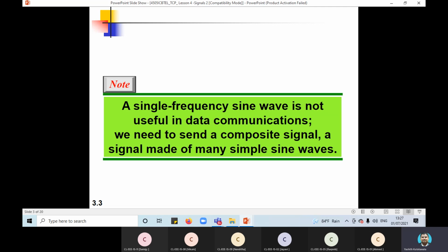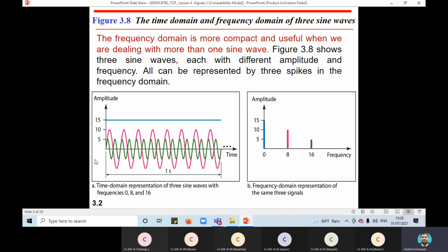the signal needs to be discrete, somehow having some constant voltage levels, a high level and a low level. Then according to the high level and low level, we can assign digits. Once you assign a logic to these levels, you can call it digitized or digital. But how can we use a sine wave which is having a constant variation all over the range? The voltage keeps on continuously varying. There are no discrete levels. So in a natural case like this, it's really hard to interpret a binary logic like 1 and 0.